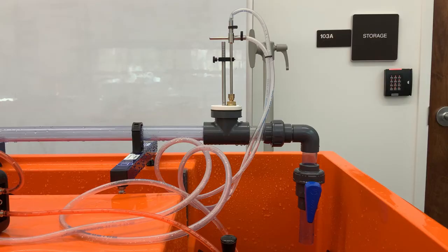So by doing this test, we will change the position of the Pitot tube inside the pipe, and we will keep the flow rate fixed. Unlike the previous part, for this part we'll keep the flow rate fixed, but over time we'll change the location of the Pitot tube, and that's how we're going to measure the dynamic pressure at different positions of the Pitot tube, and from there we'll develop the dynamic head profile. So I'll show you how to do it.